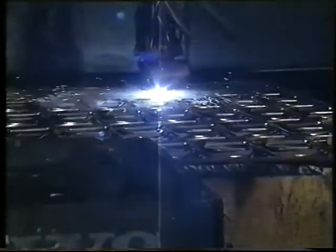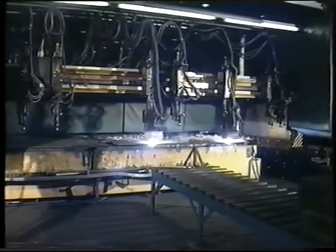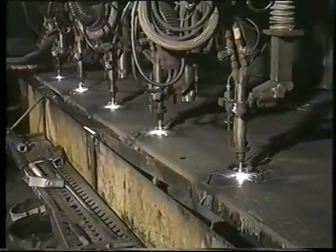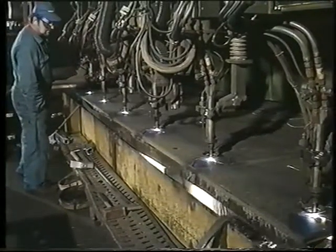Nitrogen with water injection, Volvo BM. Volvo BM uses a machine which incorporates both gas and plasma cutting. This machine can be used with either 6 gas torches or 3 plasma torches. The method used is nitrogen plasma with water injection. The machine is manufactured by Hypertherm.